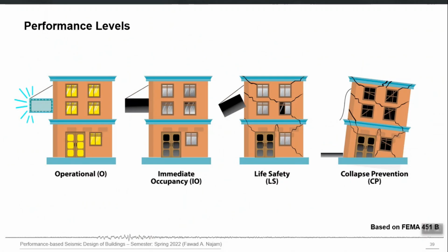Yes, obviously you can make a hazard map at any definition of hazard. Generally, the reported hazard maps are at 10% probability of exceedance, but you can also make a hazard map at 2% probability of exceedance, and the numbers will be higher. You can make a hazard map at 50% probability of exceedance in certain years. The numbers will be lower than that, right?